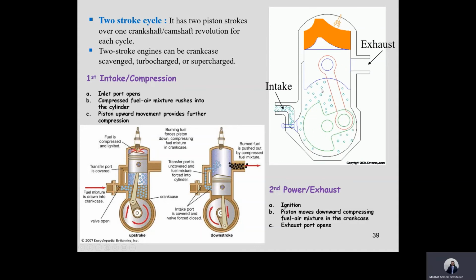So we combine both of them. But if you look at a given time, you will find the intake port and the exhaust port are open at the same time. That means some charge of air plus fuel can have a short circuit and can just escape without burning inside the engine.